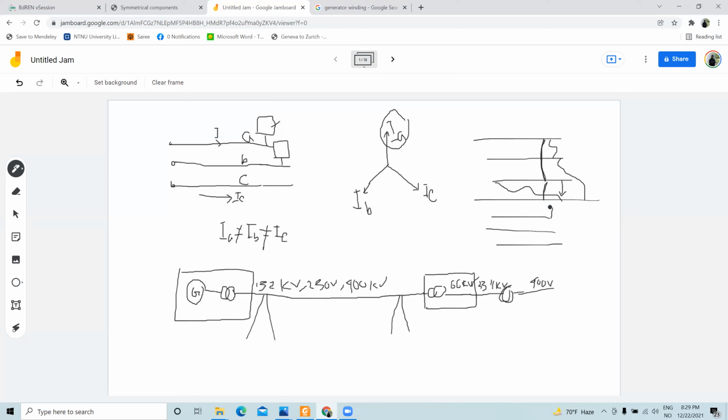Your house was connected, and your house has different loads, so the current that is coming to the load is not extremely high. The system is designed to handle this current. But if you have a short circuit, that means you are basically bypassing the load and it's connected to ground. So if a short circuit happens, at that moment a very high amount of current will flow through the system. Am I clear?